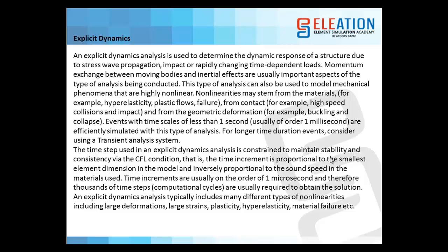What does the CFL condition mean? The time increment is proportional to the smallest element dimension in the model and inversely proportional to the sound speed in the material used. It means that whatever time step we give depends on the element size. If we give a lesser amount of time step to capture the phenomena, it will take more time because it depends on the size of the element. So if your element size is very small, and similarly you give a very small time step, then the solver time increases drastically. So you have to maintain the relation between them.